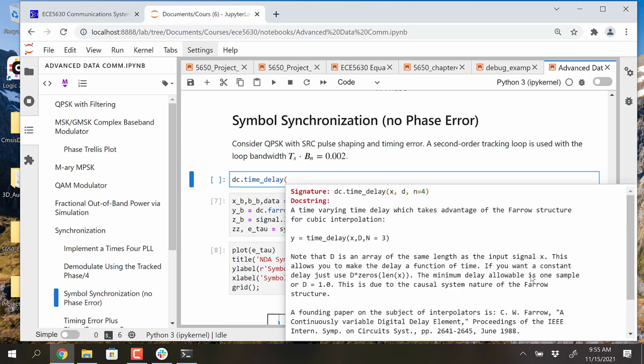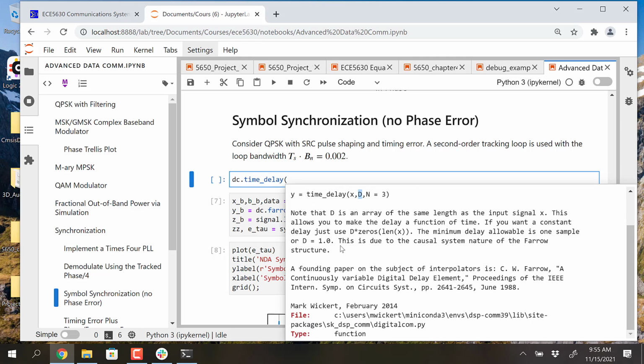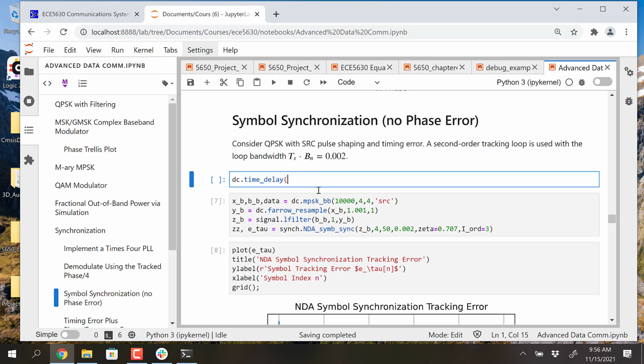Another thing I'll point out is that in the newest version of the code, D here is little d, but when my co-author was doing things, he didn't change everything in the help. So if you have d equals something in here, you've got to make sure it's little d, otherwise it's going to give you an error.